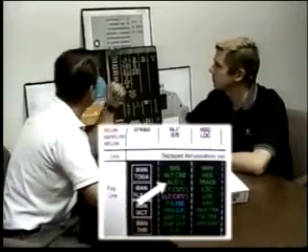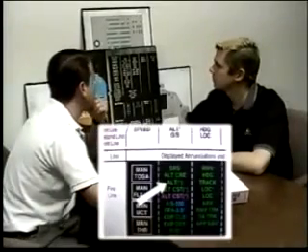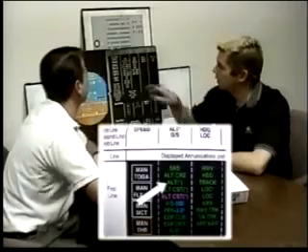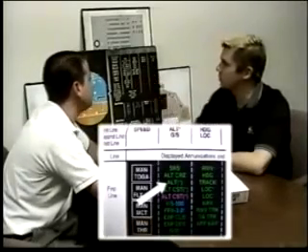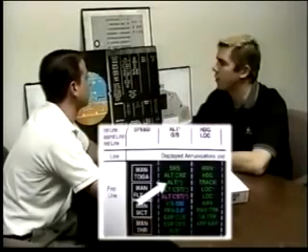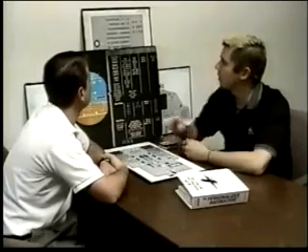And then the last scenario would be on a go-around. It'll give you V approach or whatever your current airspeed, whichever is higher. Alt star and alt. What is that? Well, on all the modes, wherever it says star, that just means capture. That means it's just about ready to engage this mode. It's like a pre-mode there. Alt is basically alt hold for any of the other airplanes that we've flown before. And it means I'm going to hold whatever altitude I have set in the FCU window.